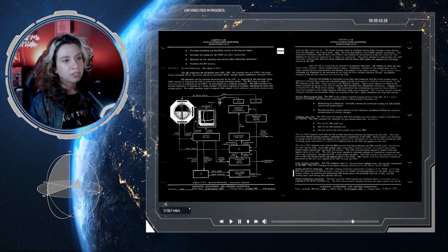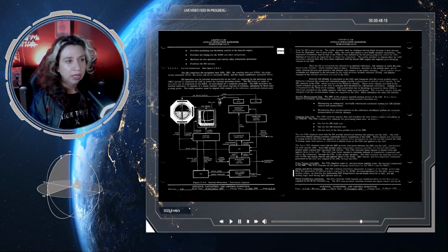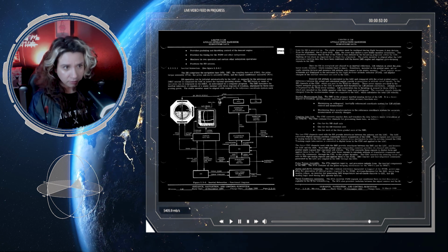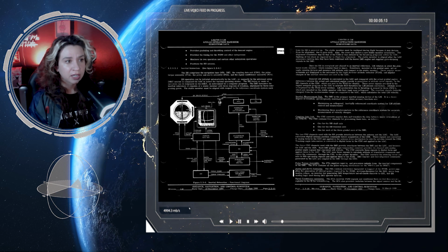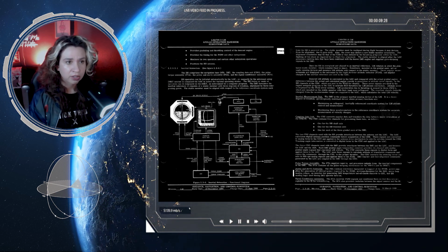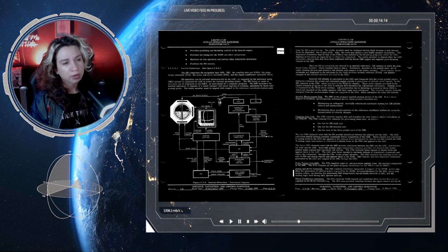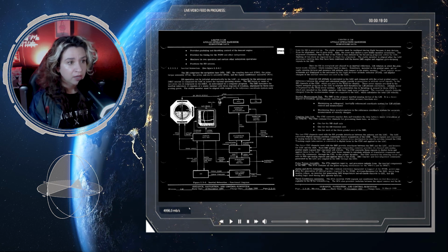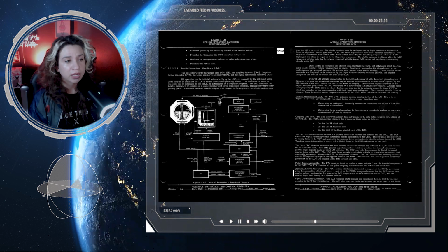LM acceleration due to thrusting is sensed by 3 PIPAs, which are mounted on the stable member with their input axes orthogonal. The resultant signals, velocity changes from the accelerometer loops, are supplied to the LGC, which calculates the total LM velocity. The IMU is the primary inertial sensing device of the LM. It is a 3 degrees of freedom, gyroscopically stabilized device whose primary functions are maintaining an